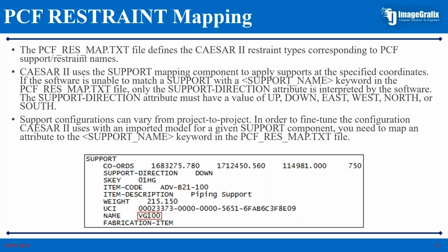I don't bother about what category the support is, how heavy it is, or what shape it is. What is that going to provide me in CAESAR II? What does this support do to my pipe at that node number? That is what a stress engineer is concerned with.